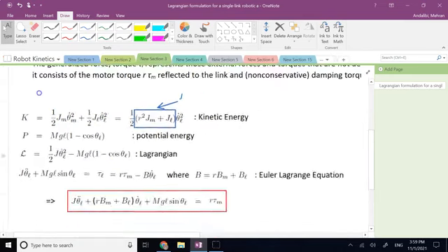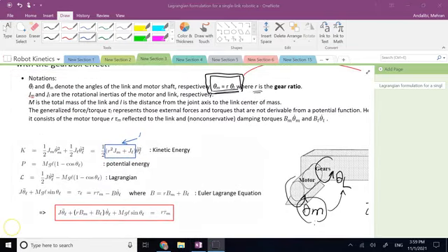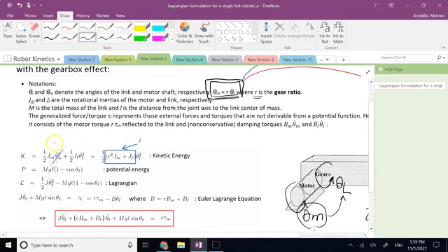L of the load. And since theta dot m is R times theta dot L, I can replace it, right? Because all I need is to take a time derivative from this constraint equation, correct? And that means I can eliminate this theta dot m term as, when you square it, it's going to be R squared theta dot L squared. And if you factor out theta dot L squared, this is what we call J equivalent or J effective.